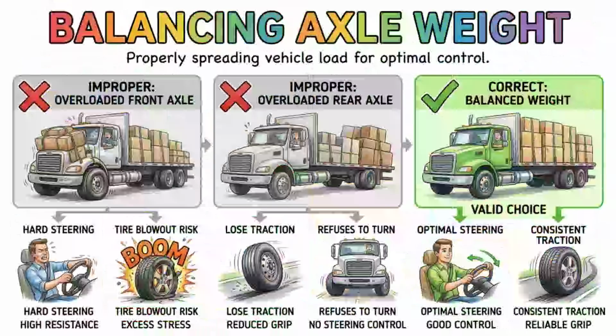Loading and boarding passengers requires patience and clear communication to avoid slips, trips, and falls. You must always wait until your bus is completely stopped and the parking brake is set before opening the doors to let people on or off. During the boarding process, you must ensure that all aisles and stairwells remain completely clear of baggage, as blocked aisles prevent safe evacuation during an emergency. You should safely stow larger bags in the designated exterior compartments and ensure those compartment doors are securely latched shut before moving.